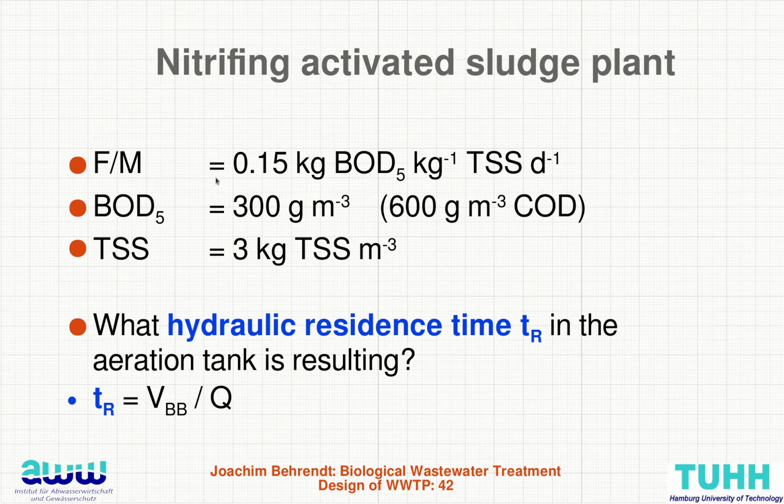Finally, to calculate this, if you want to have nitrification, you are choosing the 0.15 kilogram BOD per kilogram TSS a day, assuming 300 grams per cubic meter BOD, also 600 grams per cubic meter COD, half-half, and 3 kilograms TSS.